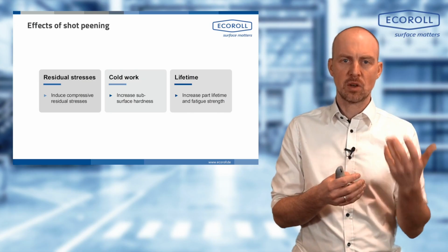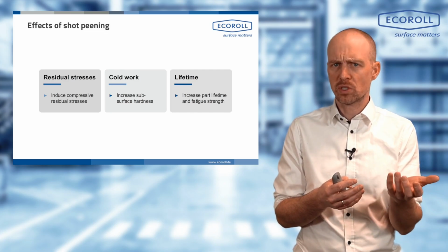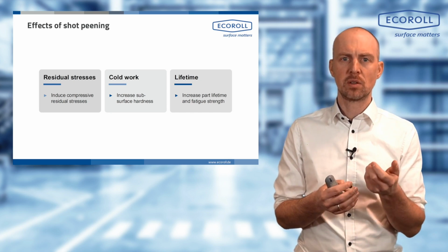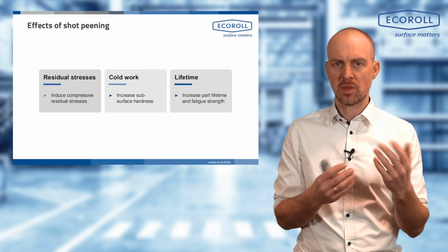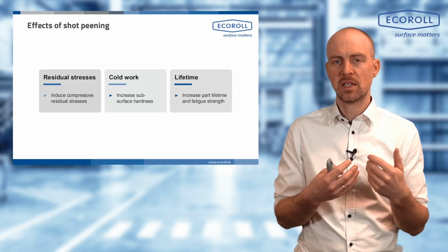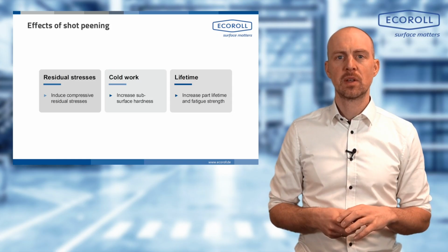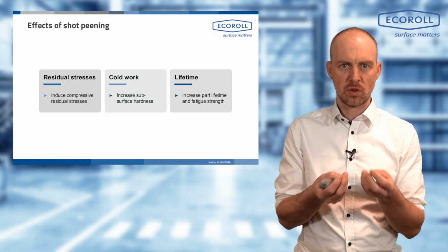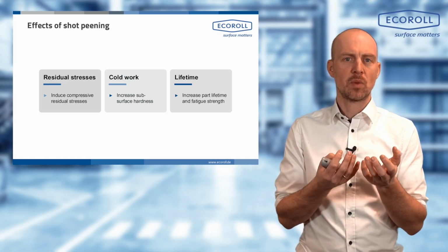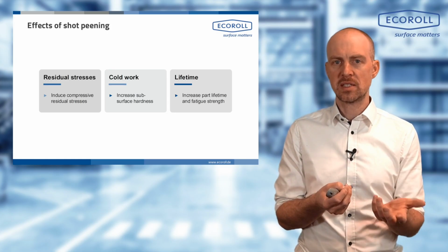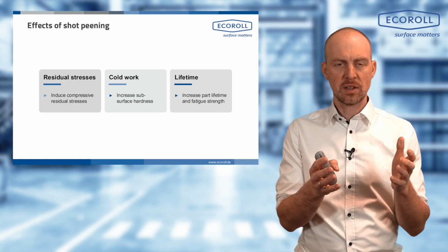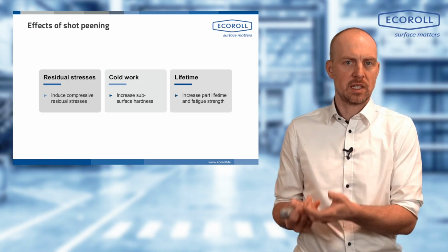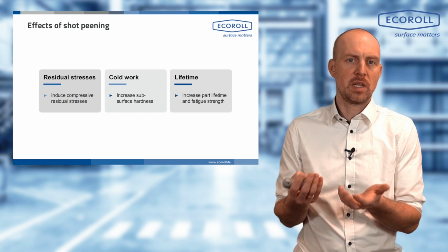If we look at that, compressive residual stresses are created in the surface, which can also be quite high. So we really create very high compressive residual stress here, sometimes in the range of the maximum that a material can withstand or even sustain in terms of compressive residual stress. Through the impact of the blasting media and this mechanical change, this plastic flow, we create cold work by increasing the dislocation density. And all of this together then leads in the end to the fact that, as a rule, the service life of our components is significantly increased. That's also the reason why shot peening is frequently done.